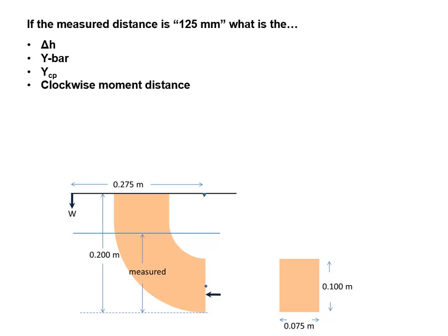In the case of it already being partly submerged, like here's the water and here's the plate, then the hydrostatic force distribution is going to be a little bit more, a little more. So it's increasing, and if you go really, really deep, then the top edge and the bottom edge aren't going to be very different. Like, you know, the center of area for a triangle is 2/3 of the way down, but it's not going to be 2/3 of the way down for a shape like this.